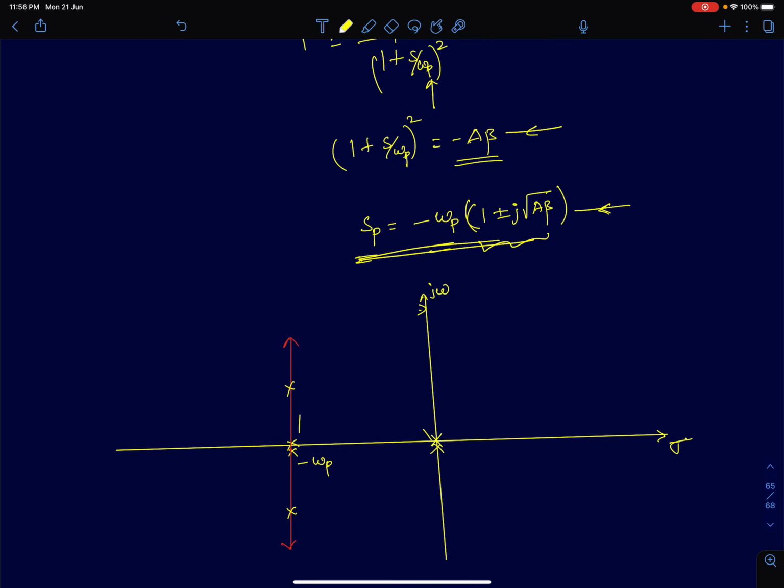As you vary the loop gain, the real part remains unchanged, but only the imaginary part changes. As you increase the loop gain, the poles move further into the complex part, and the poles become complex conjugates. We started with real poles, but the poles soon became complex conjugate.